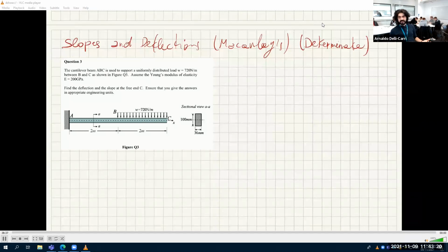If the beam is over-constrained, you can't use just equilibrium equations. Remember what I told you last year: determinate beams are what we do now because we only need to solve the equilibrium equations. When we deal with indeterminate problems, we need to take into account the deformations. We start with determinate beams, and then we're going to solve an indeterminate beam by making use of the fact that we know how to calculate the deformations, and that at the constraints, some of those deformations are 0.